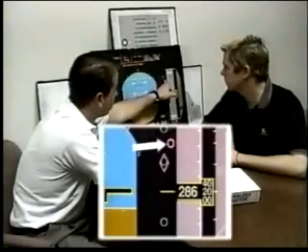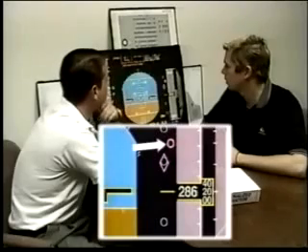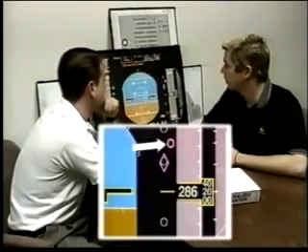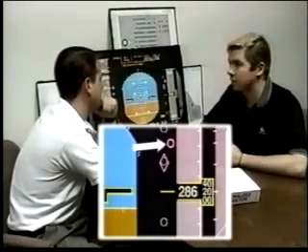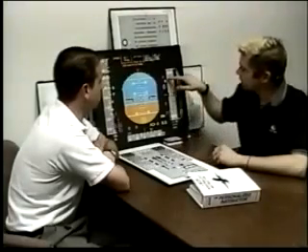Along to our magenta donut. What do we call that, and what's it displaying? It's the vertical navigation deviation indication, VNAV deviation, or magenta donut, which is what we really call it. What it tells us is how far off we are from our vertical navigation path, the VNAV descent path. The scale is plus or minus 500. We can see a more accurate version of this on the PROG page, but it doesn't give us a graphic definition.